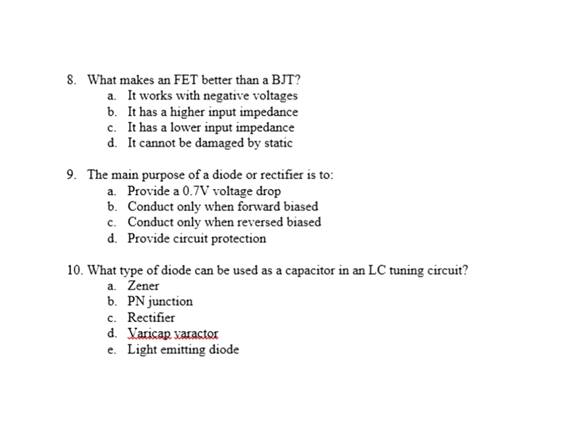Okay, 8, 9, and 10, rapid fire. What makes an FET better than a regular old standard transistor? What did we say were the things that made it better? Do you remember? What were they? Well, it has a high input impedance, a high Zin. And what kind of signals does it amplify? Does it amplify current or voltage? It doesn't use current to amplify. It doesn't use current on the controlling terminal. It amplifies changes in voltage.